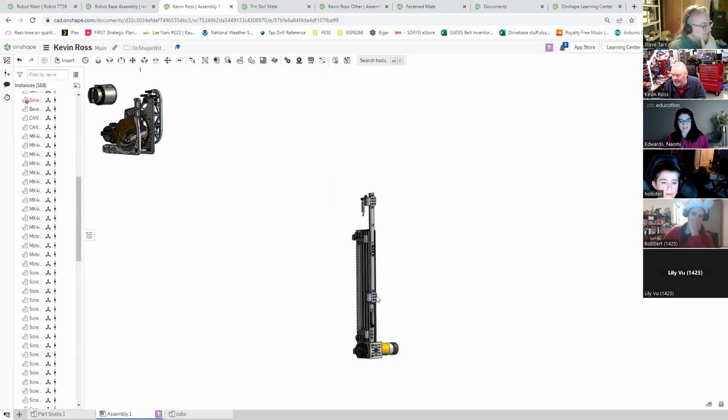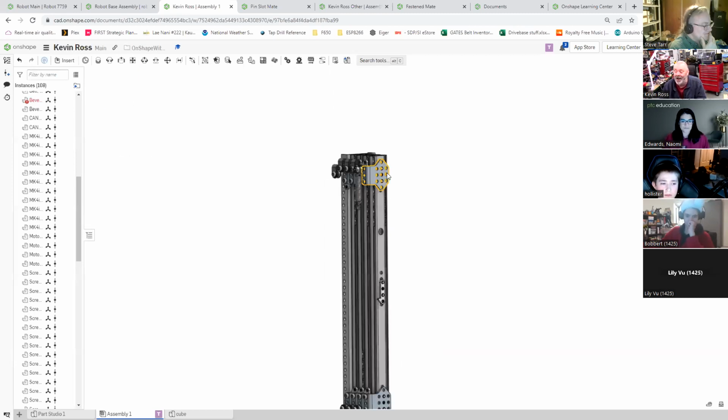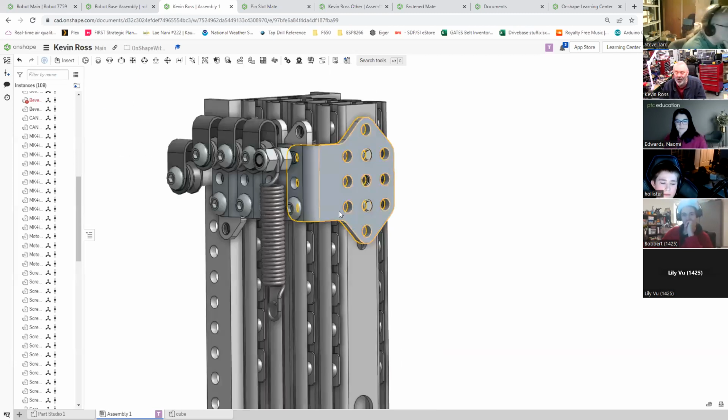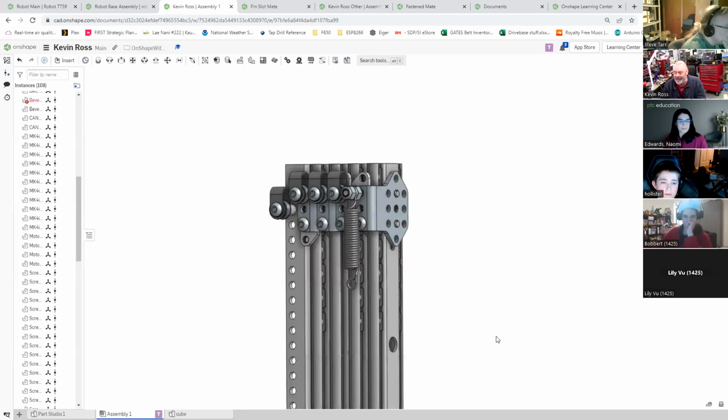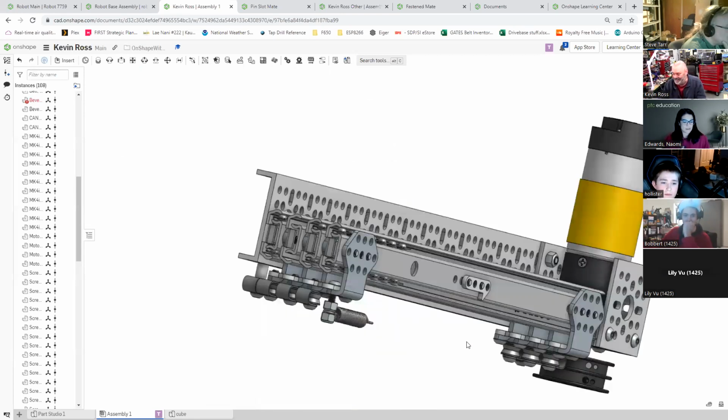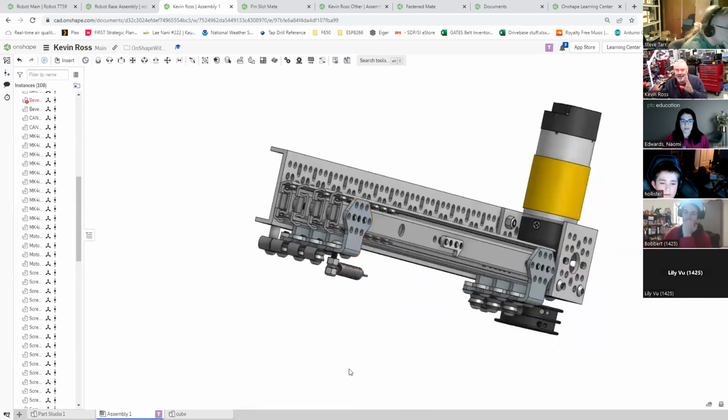so what I did is I'll show you how you can go about making this work without having to figure out every little detail. I did not go through and do all of the connections, all of the mating on this, but I did group and mate, which means taking a bunch of things and saying, all of you parts, you stay in relation to each other, don't move, right?